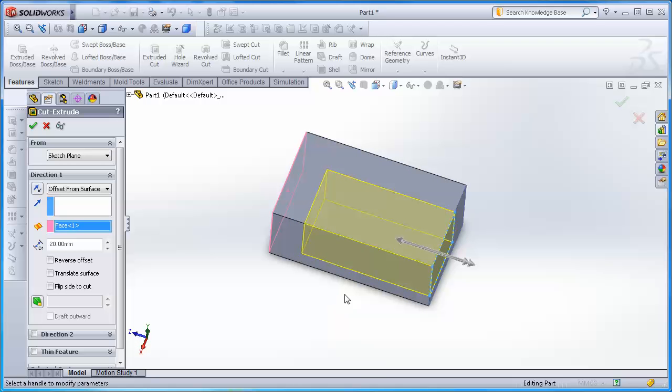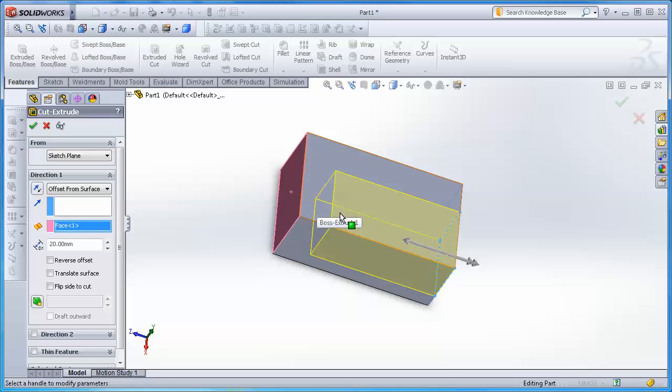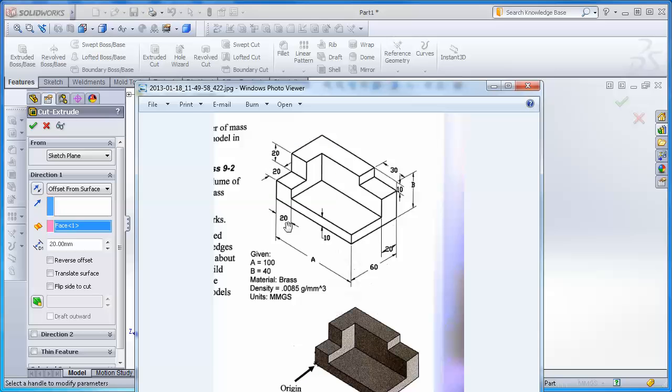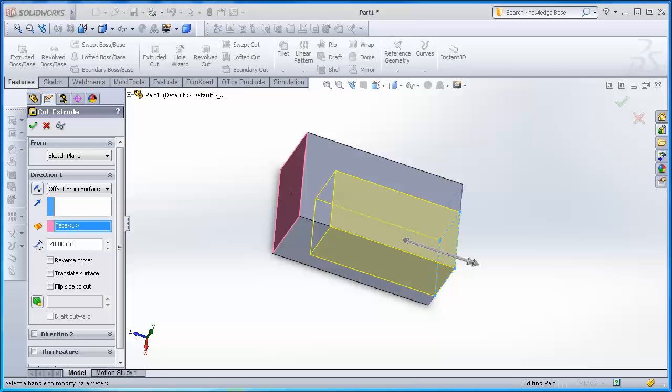This is mildly advanced. Okay, and I actually have never done it before, but that's okay, but it makes sense in this case. It says here's my plane. I want to go until I am offset from this surface over here a certain amount. And that actually lets me type in the 20, which in looking at the part is more like what I believe the designer of the part intended. They would much prefer I type in the 20 and not the 100 minus 20. So we've achieved that with the offset from surface.